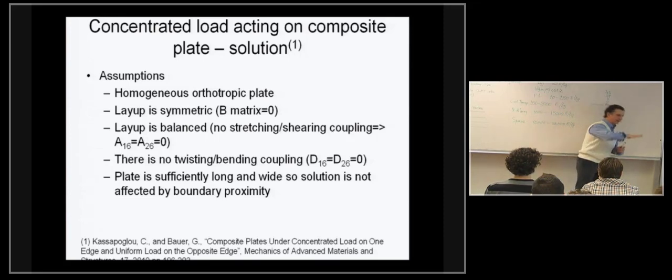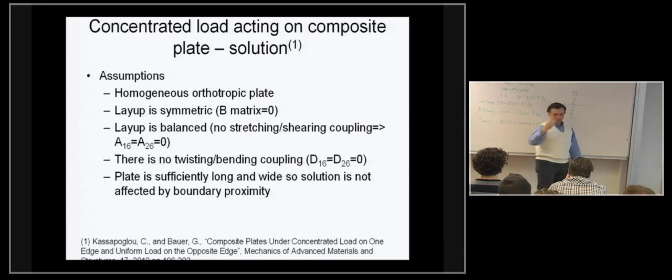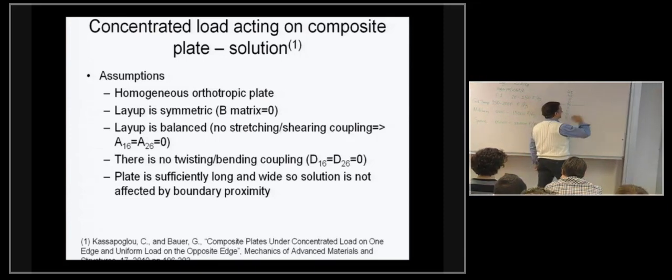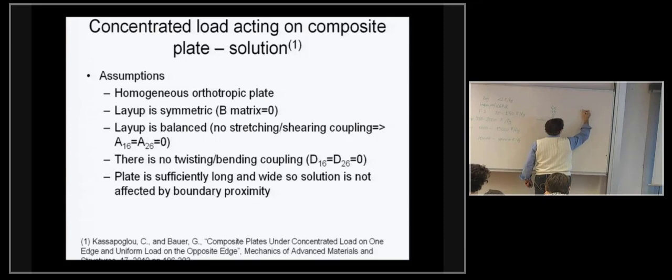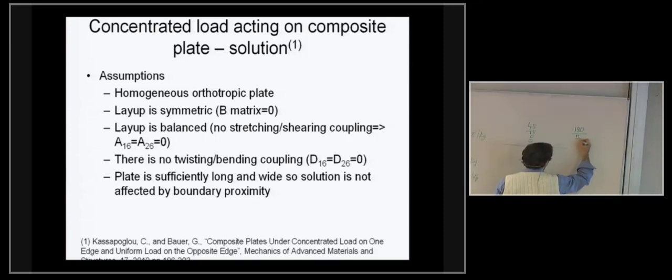But instead of having an infinite number of fibers distributed every degree, you can do it every certain intervals of degrees. So the quick way to do this is you take 180 and divide by n divided by 2. So if you have n layers, you divide it by 2, you get 4.